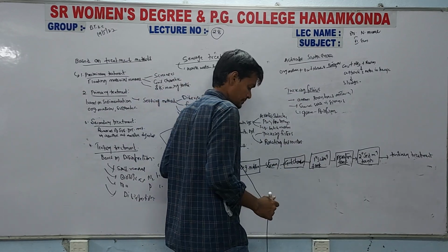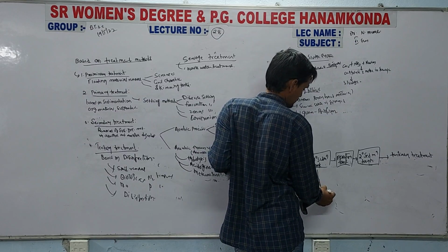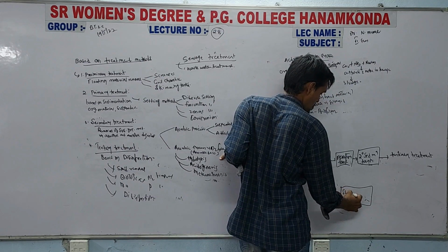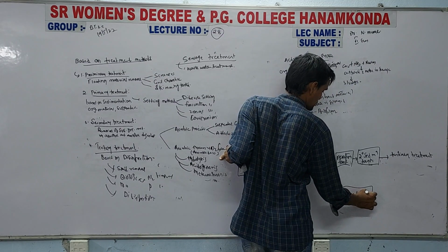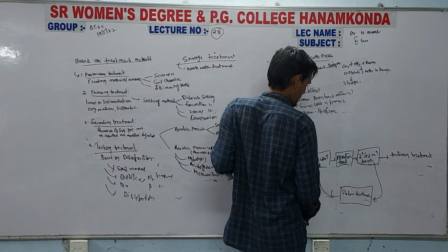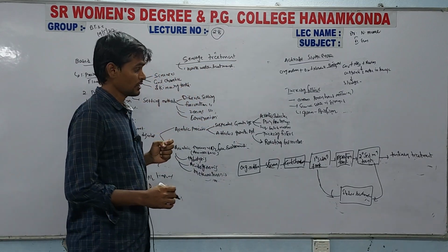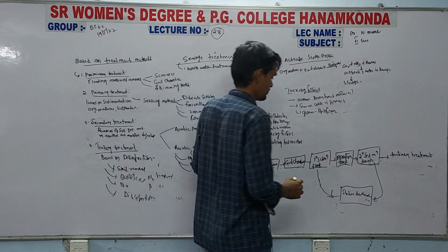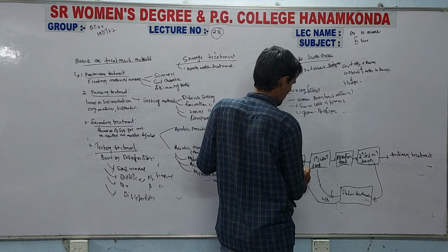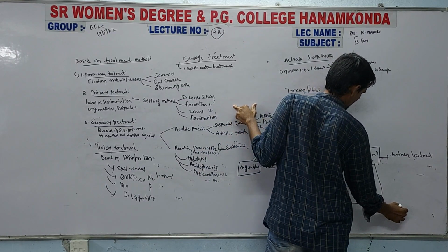So, from the primary sedimentation tank the sewage goes to sludge treatment, and the secondary sedimentation tank also goes to sludge treatment. So, the material from the primary sedimentation tank and secondary sedimentation tank goes to sludge treatment. Whatever the suspension, it goes back to the grit chambers and the sludge will be disposed.